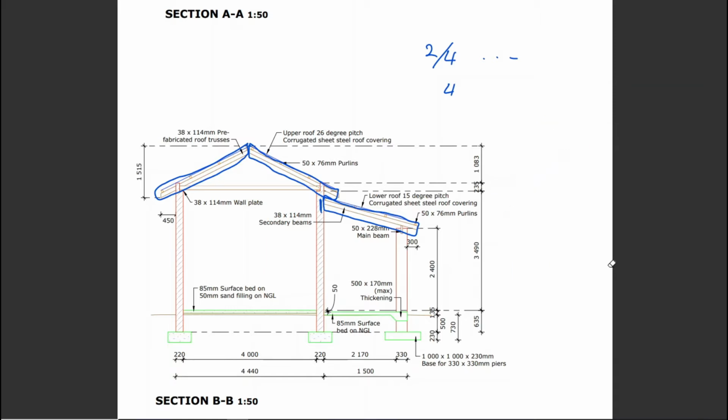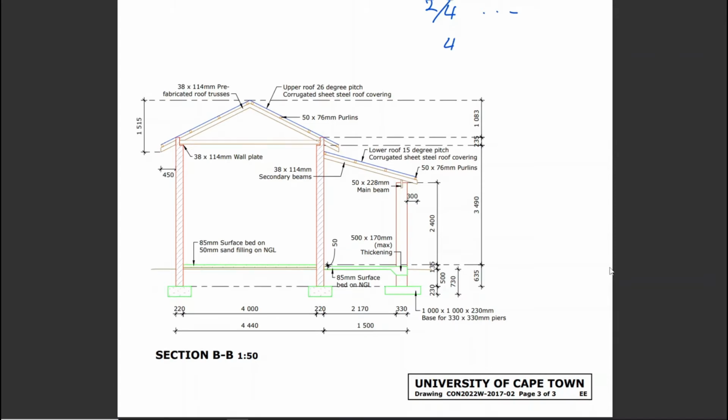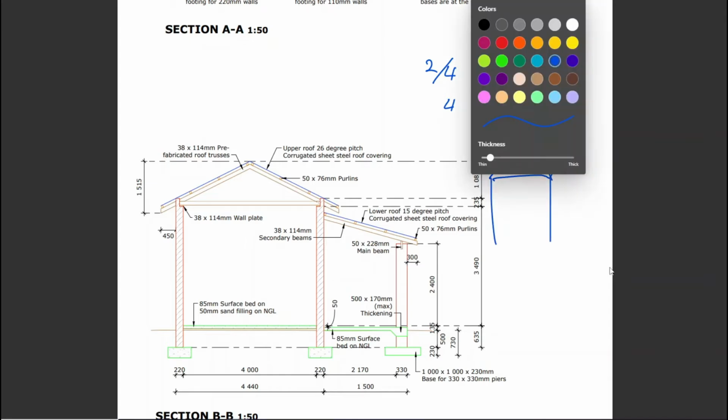So those will be the same, but what's interesting is the difference in calculation for your fascia boards and your barge boards. So fascia boards are running with your building. So let's just make a nice little drawing here. And since fascia boards are running with your building, they don't get a factor. You don't multiply it with a factor, right?